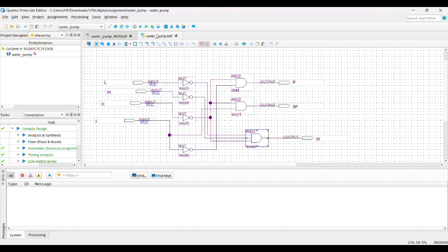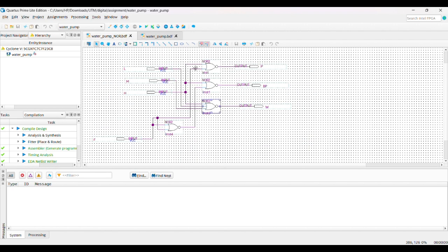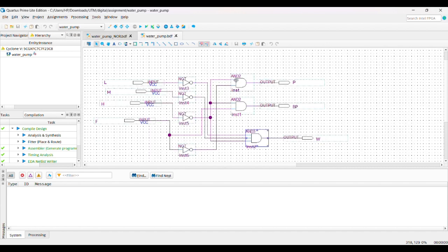You can see that the NOT gate is disappearing because we put two bubbles at the back of the AND gate, and then we pull the bubble back, and it will collect to the NOT gate, and then the NOT and the bubble will cancel each other.